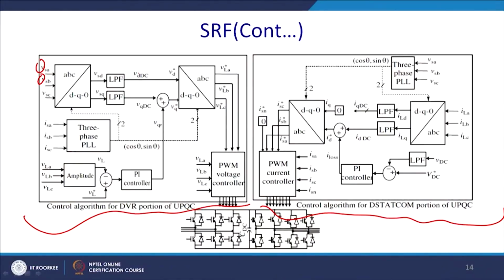So, when you pass this through the low pass filter, the frequencies that correspond to 50 hertz will pass, and will look like a DC in the DQ frame. So, ultimately you will get a Vd reference for the fundamental; all the harmonics will be truncated by this low pass filter.